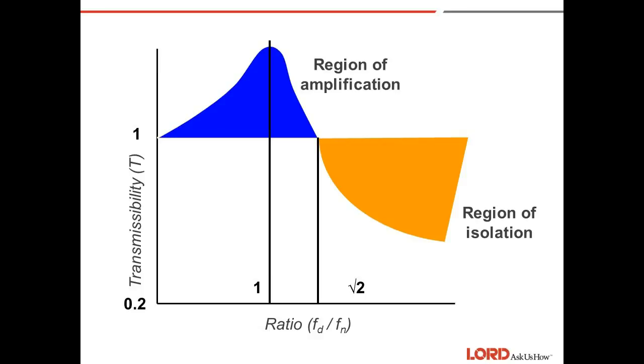Usually, this is the goal of an isolator spring design. We wish to attenuate a disturbance of a particular known frequency. From the desired transmissibility, we can define the required frequency ratio and calculate the system natural frequency. Then, using the natural frequency calculations, we can calculate the required spring rates for our elastomeric springs.